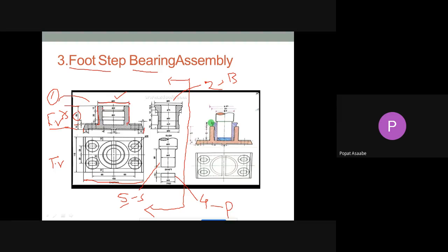Okay, then we want to draw this portion. मला हे पोर्शन ड्रॉ करून घ्यायचं आहे. Then tell me what is the diameter of this portion? या हातल्या लाईनचं डायमेन्शन त्यांनी किती दिले आपल्याला? Yes, 62. म्हणजे आपण काय करायचं आहे? From the center point we want to divide this 62, half part in this direction, half part in this direction. म्हणजे इकडे साईडला किती घ्यायचं आपल्याला? 31, 31 and this line we can draw. त्याची हाईट किती दिली? 12 दिली. Okay, this portion we can draw easily.